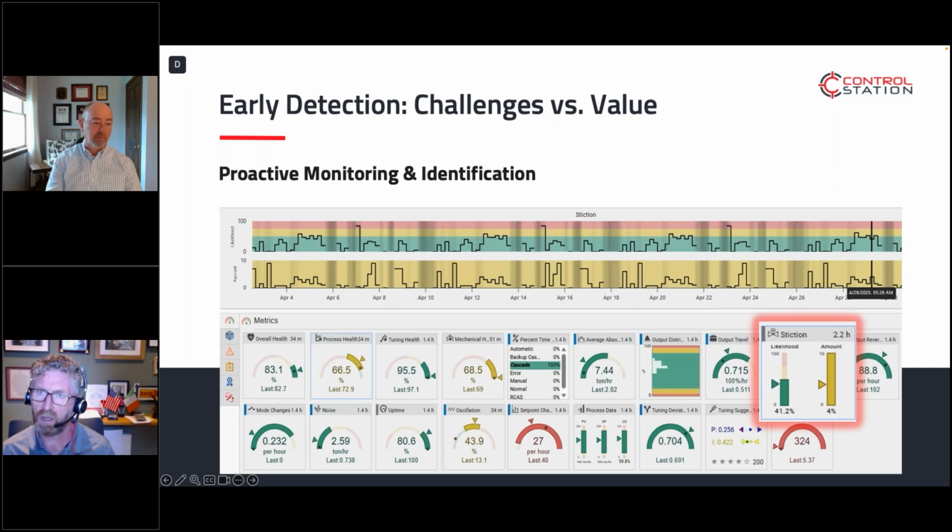We are seeing events that are exhibiting stiction type characteristics, and we start to analyze that and metricize it. Once the likelihood starts to become significant, above 30–40%, we can say, and you can see on the top chart there, the likelihood is quite consistent across the range.